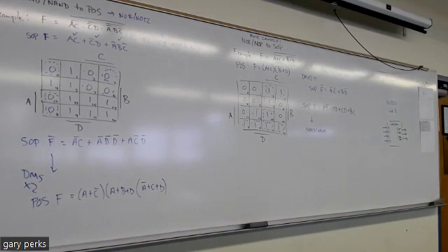Yeah, this activity, the first problem, it has an output with a dash. What does the dash mean? You remember what a dash means? Right, so don't care. You can make it a 0, 1, whatever's gonna lead to the most reduced expression.